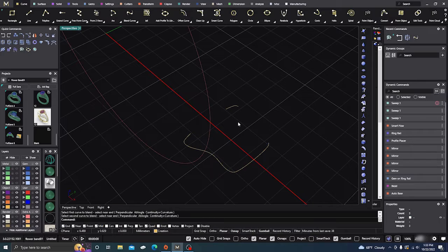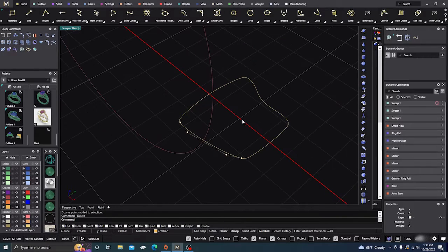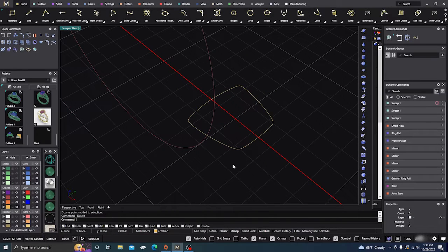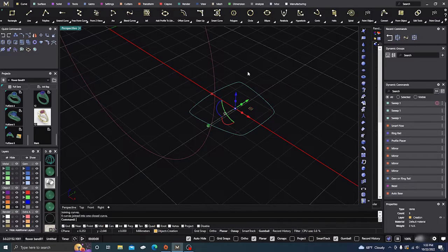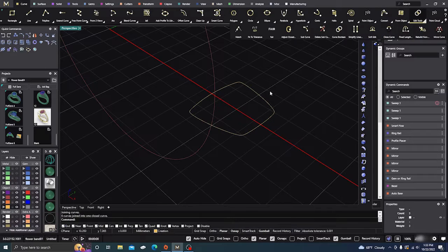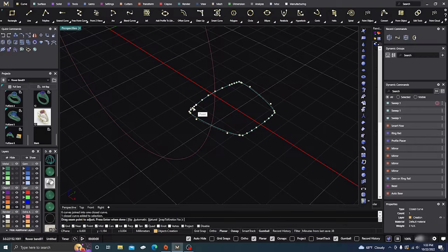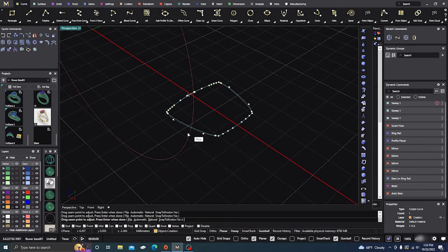And then from here I'm going to right click, and I'll do it from here and here, and enter, and get rid of that. Now let's do a blend curve here to here, here to here, here to here. Alright, this curve still comes in, so I'm going to take these 2 points and delete them, and I'm going to do the same thing over here. So there we have a little bit more uniform curve. So I'm going to join them together, and we're going to check our seam point because I didn't do that last time. And where is it? There it is. And we'll take it and drag it to the mid. Alright, and hit enter.